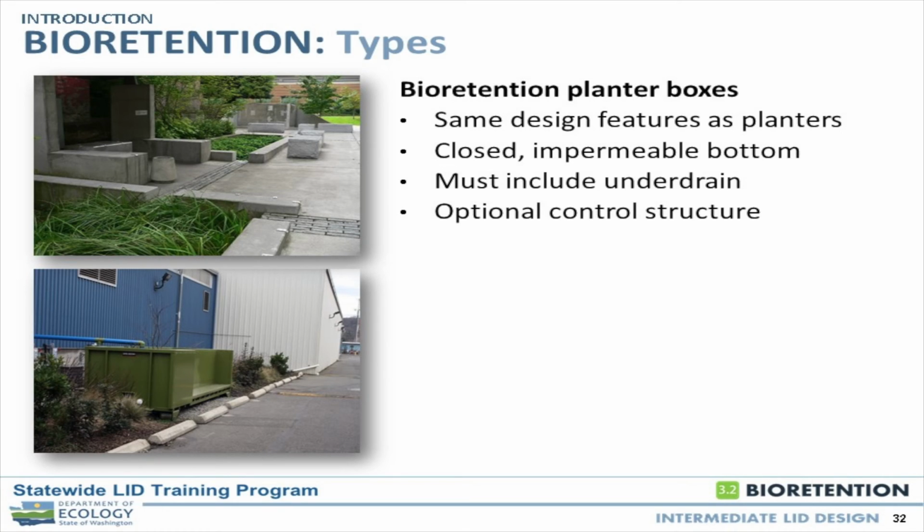Planter box, fully enclosed, so what? It has to have an underdrain, right? You have to design that in. And again, it may or may not have a control structure.